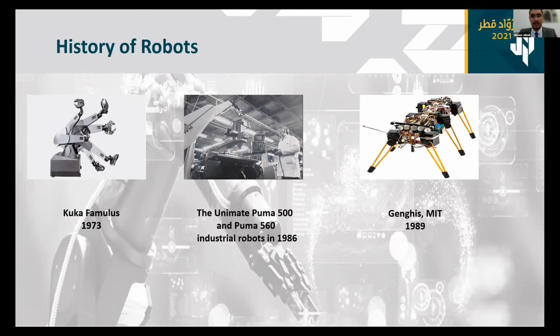In 1989, Honda began its humanoid research and developed a program to create robots capable of interacting successfully with humans. A hexapod robot named Genghis was revealed by MIT in 1989. Genghis was famous for being made quickly and cheaply due to the construction method. Genghis used 4 microprocessors and 22 sensors with 12 servo motors.